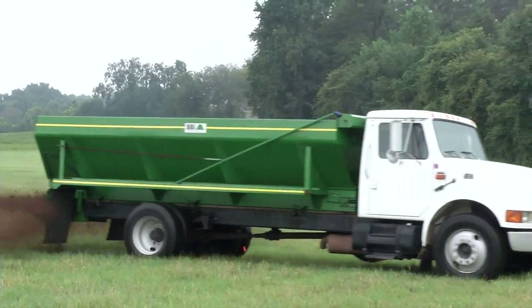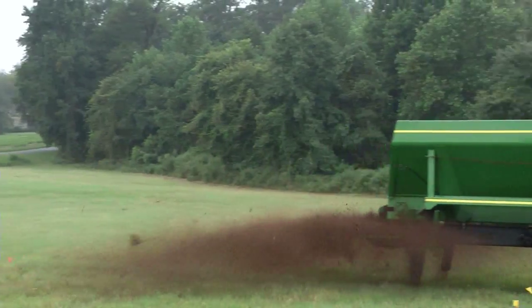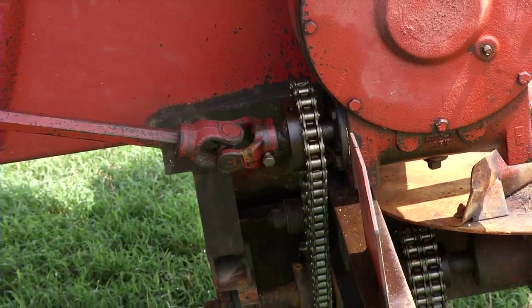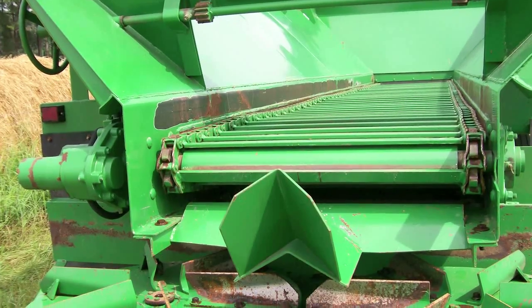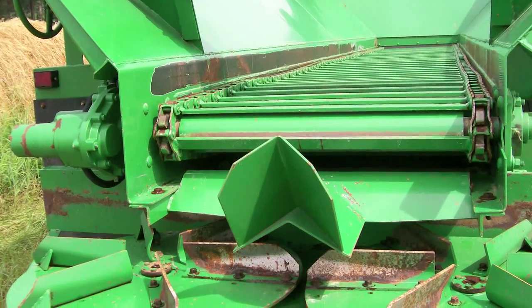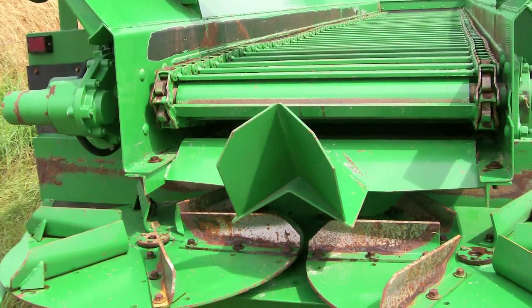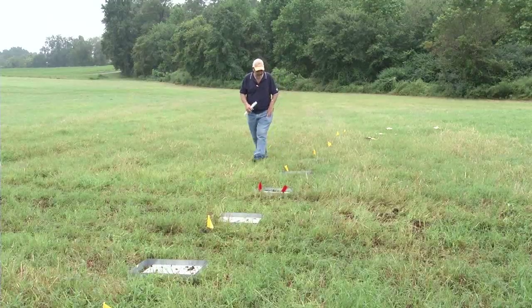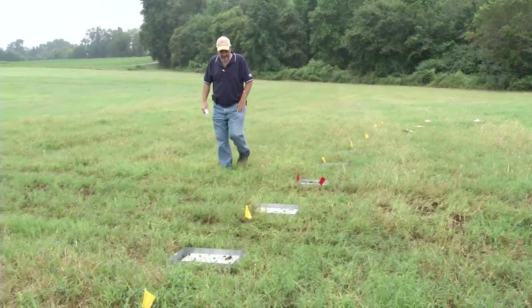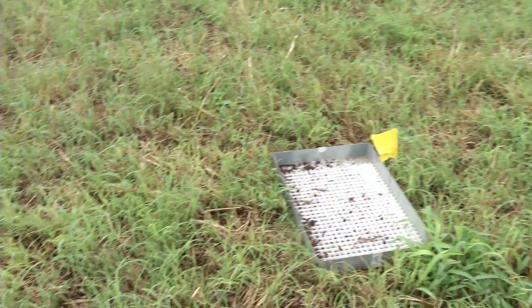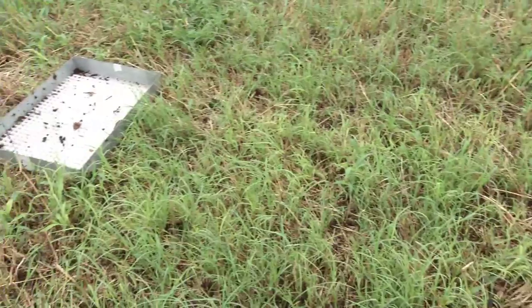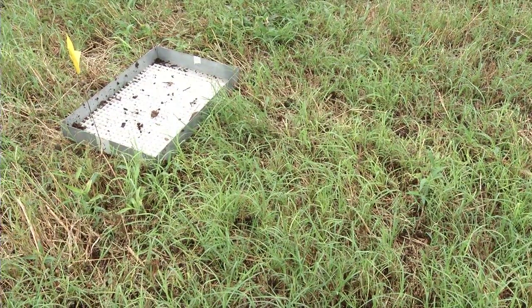We can change the application rate by changing the driving speed, chain speed of the conveyor, and the gate opening. To improve pattern uniformity, we can increase the spinner speed or reduce the distance between the hopper bottom and the spinner discs. If we have problems with our spread pattern, we can do several things that we will discuss later. Both rate and uniformity are greatly influenced by the litter properties, so the general guidelines provided by manufacturers on swath width may not apply to a particular situation.